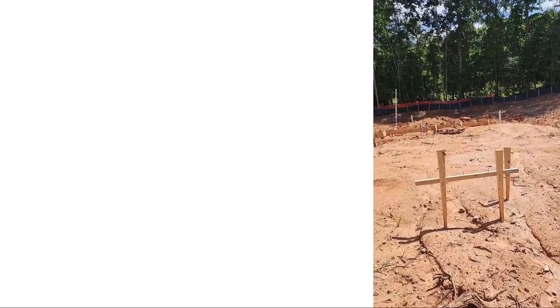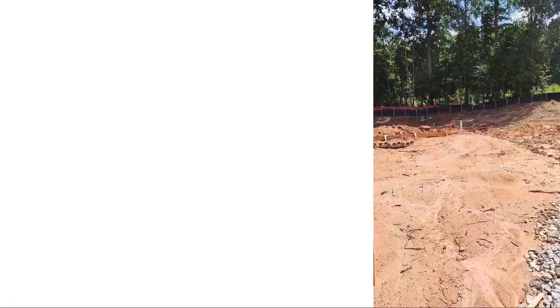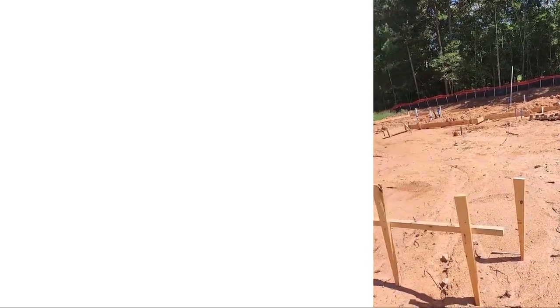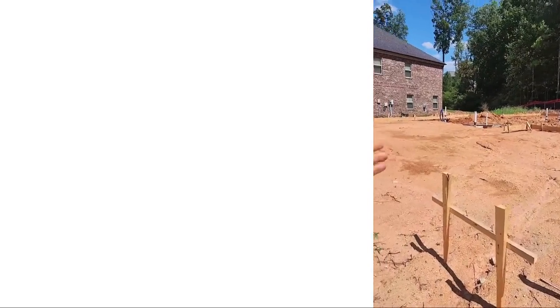All right, team. So as you can see from our site plan, we have the perimeter of the property. When we get to the perimeter of the property, we are going to form a board. That's the first thing we do. We're going to form a board that's going to outline the perimeter of the property for the foundation. Okay, so what happens is, per our site plan, we're going to come in from the construction entrance, and then we're going to come all the way through, and then we're going to turn into the driveway.